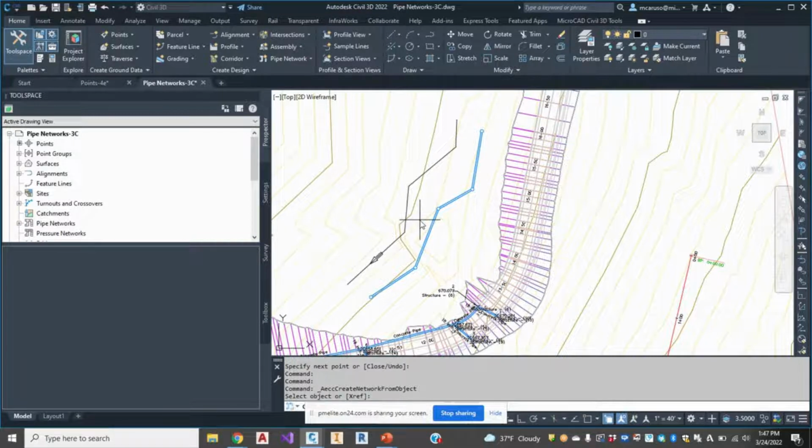So there's your time savings: we can treat all these as one and get one conversion at a time. Now you may ask, why don't we just join all the lines together as a polyline? It is another step, but in some cases we need to preserve the geometry, so we would do that.